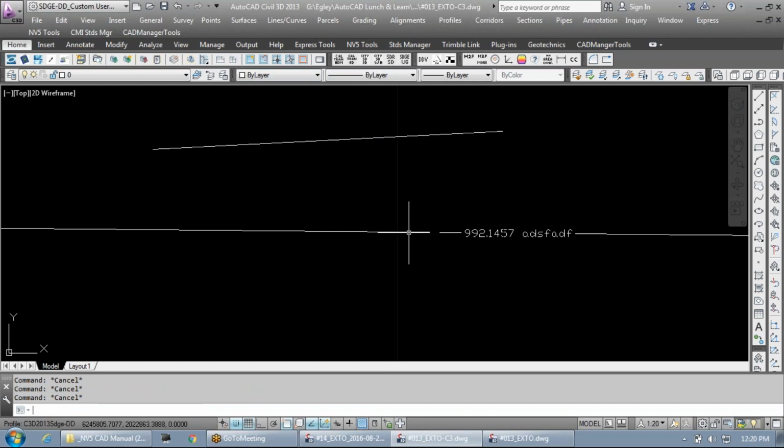You may find it necessary to draw something hard set if you want to see some differences, but the better practice is to create a temporary layer, set that layer to a weird color, like a cyan or something you can see, and then once you're done, just change your layers, right? So be sure you're not hard setting things.